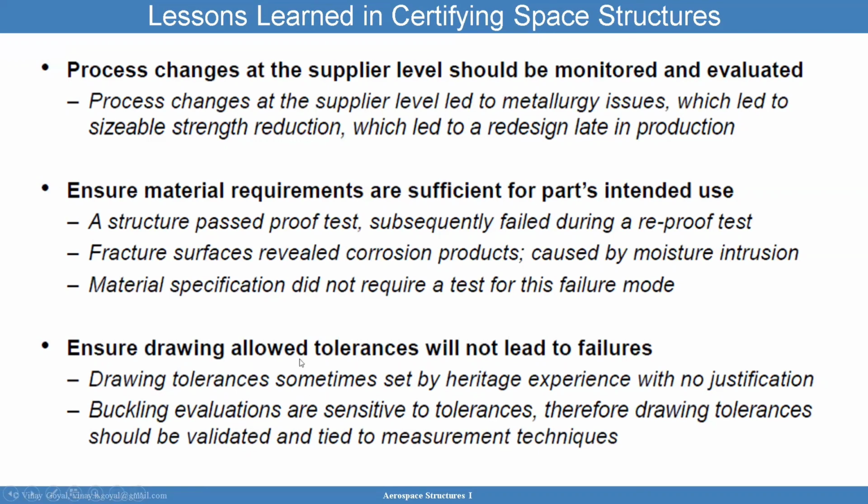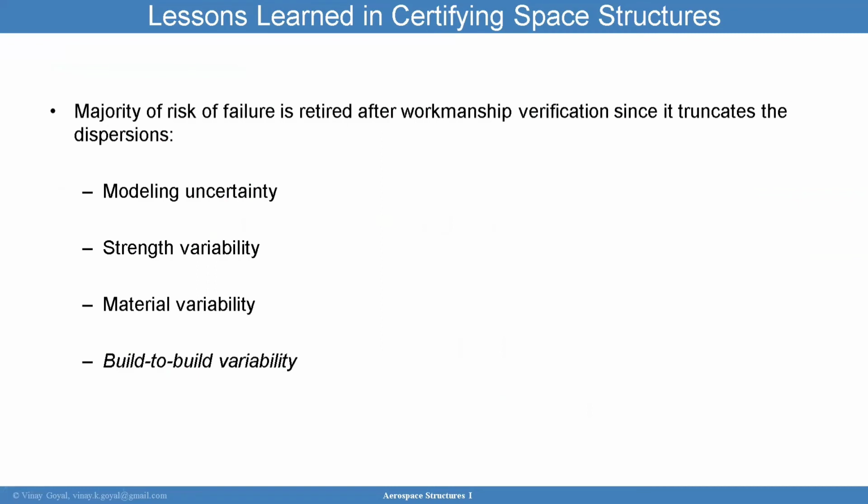And sometimes it's actually a good idea to analyze to the minimum and maximum tolerances to make sure you're not missing something. Buckling evaluations are very sensitive to tolerances, and so therefore drawing tolerances should be evaluated and should be tied to some sort of measurement technique.